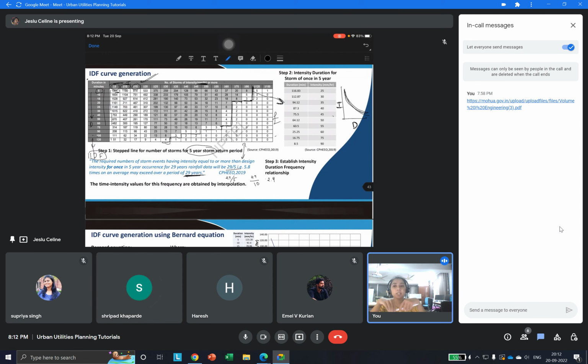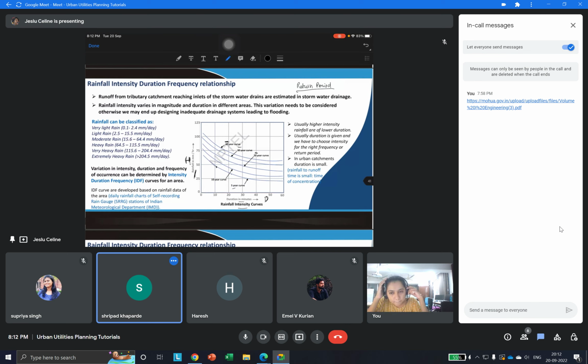And what is the representation of area? Area representation, where the gauges are, the area where the rainfall is represented. So we learned the Thiessen method of calculating the area, right? That is, you make Thiessen polygons or Voronoi polygons, and based on that, you calculate how much of the area comes under that rain gauge. Remember that in one of the initial lectures we had? So imagine you have that area and you have certain rain gauges, then we draw perpendiculars between them, and then we cut them, and then we say that, okay, this much area will come into this rain gauge, this much area will come into this rain gauge.